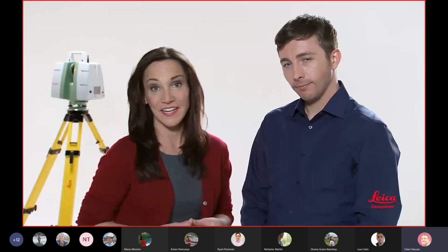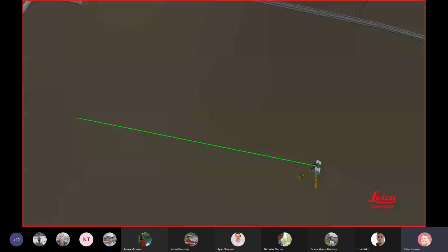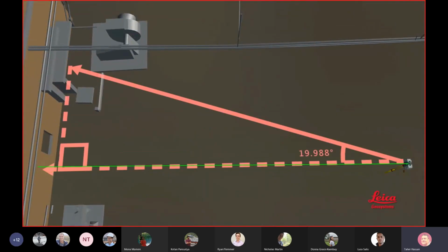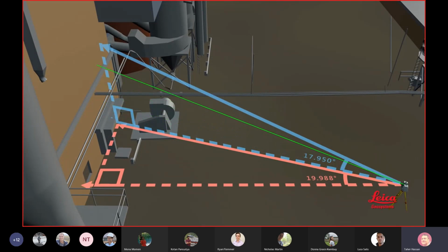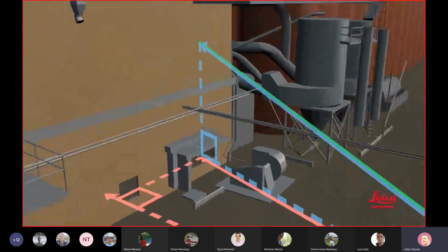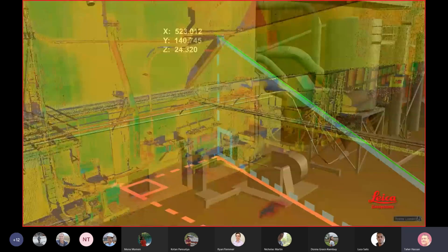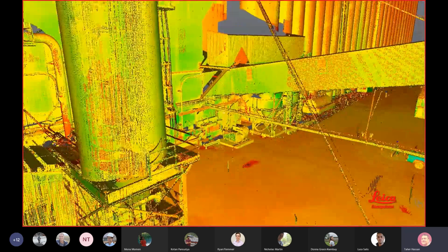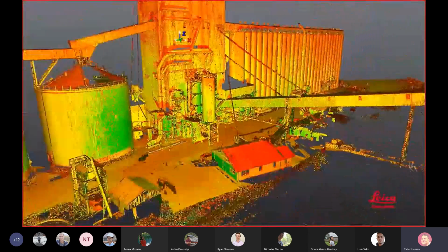But there's more to 3D scanning than just measuring distances, isn't there? Yes, for each distance measurement, additional critical data is recorded, including the corresponding horizontal angle of the rotating laser and the corresponding vertical angle of the moving mirror. The scanner automatically combines these to calculate a 3D X, Y, and Z coordinate position for each point. The resulting scan is a set of 3D coordinate measurements. It's a detailed 3D representation of the scene, often called a point cloud.